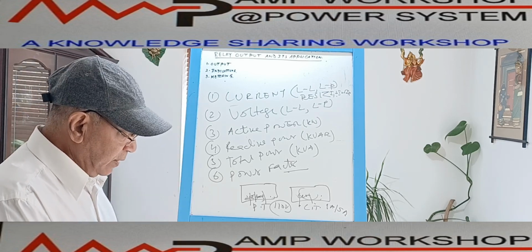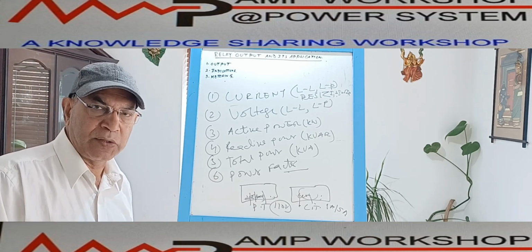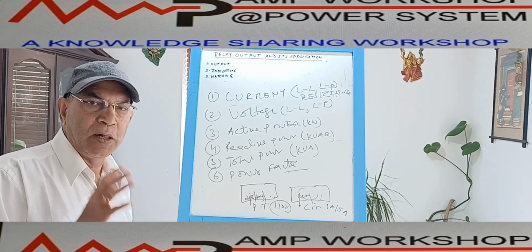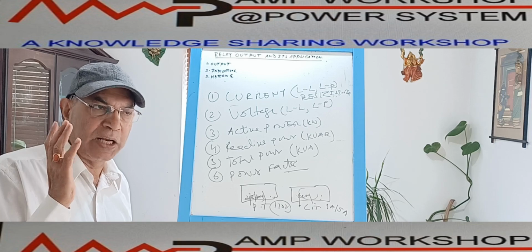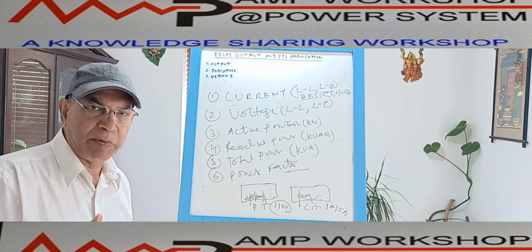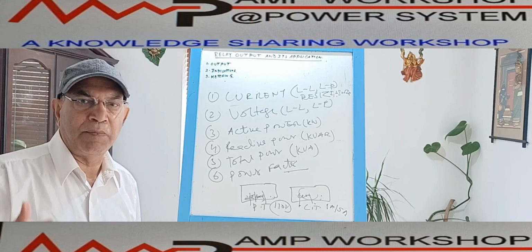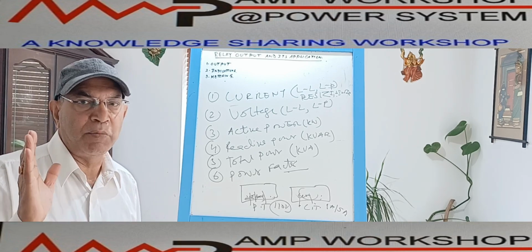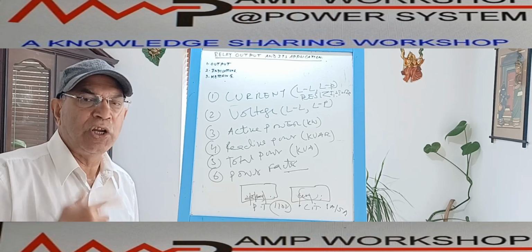So in brief, this intelligent protection relay has multifaceted facilities. It will do its main protection functions. Along with this, it can control the circuit breaker. It can give all the alarm indications of the circuit breaker. It can be used as a switchgear interface for the various control interlock indications. It can be used for metering purposes. It can be used for various outside solid state devices like a laptop, hard drive, and various interfaces. It can be used for serial communication through the serial port. It can be used for the optical connection to the remote end also.